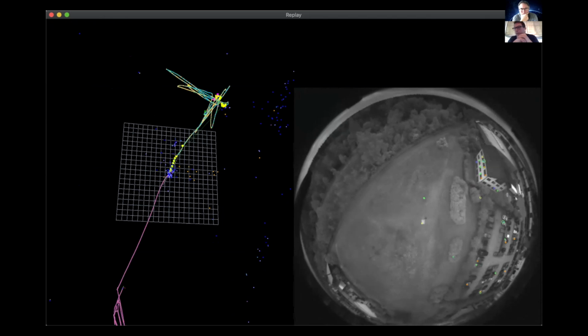So we're limited computationally. Over time, we've used fewer and fewer features. When you run this on an x86, you can run hundreds of features. When we run it on the embedded system, we run significantly less than 100 states total, including the features and the IMU states. So we're estimating the IMU biases, we're estimating the position and location of the device itself, and we're estimating the locations of where we detected features over time. So there's kind of a bit of a mini bundle adjustment going on. But it's all inside the EKF.